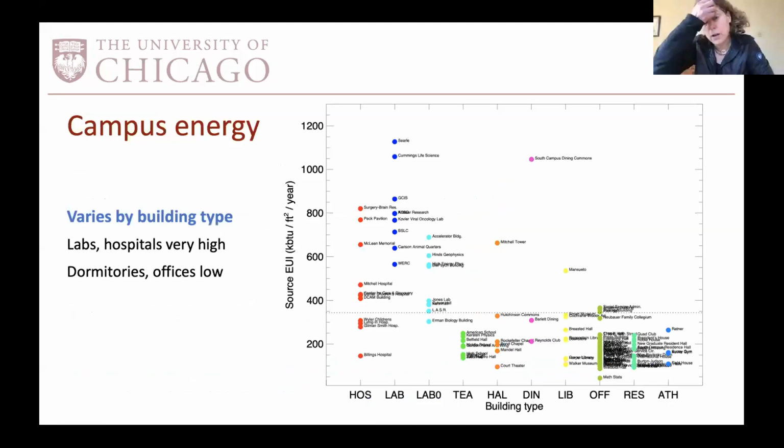So I'm going to show you, again, this is 2015 data. I have not put this in the standard units that are the ones that any scientist would like. What I'm trying to show you is energy, so power, power per area of building. And instead of showing you the normal SI units, which would be watts as a power unit and square meters as the unit of area, we're giving you these horrible English units of 1,000 British thermal units per year as our power units per square foot, because that's what engineers use. And so we're going to use those just because everyone else uses them. They make scientists' heads hurt, but it's just a simple conversion.